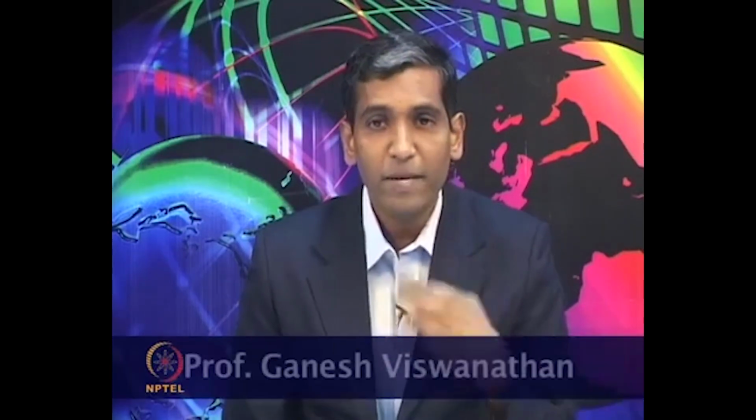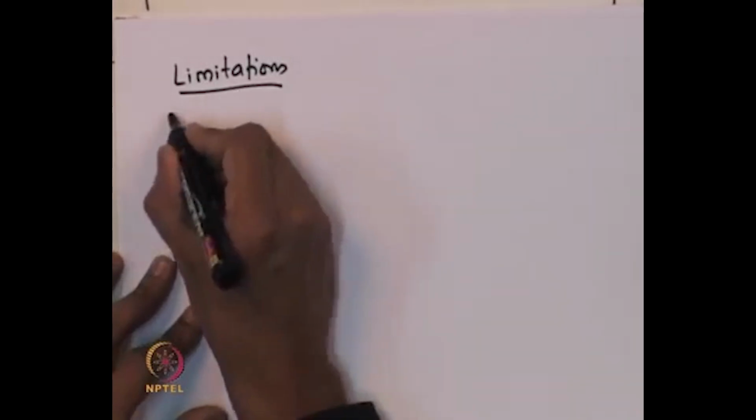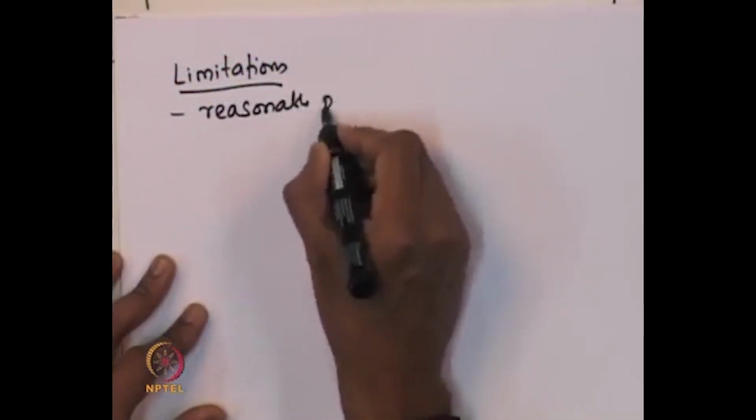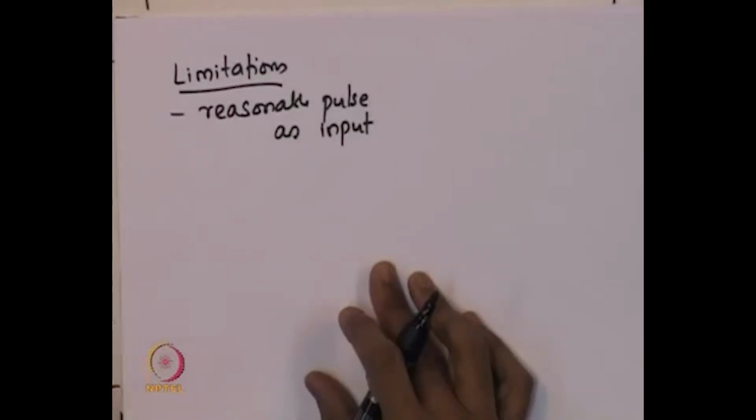Now, the question is how good is this pulse input method? Can it be used in all situations in order to find out the residence time distribution function? And that is really not the case. There are certain limitations. It is important to obtain a reasonable pulse as the input, and that is often not very easy to do. Why is that? Because the injection has to be done in a very short period, and a sufficient quantity of the tracer has to be injected in this very short period. That is not a very easy task, and it is not very easy to perform such an experiment where the tracer is actually injected into the stream in a very short time and sufficient quantity.